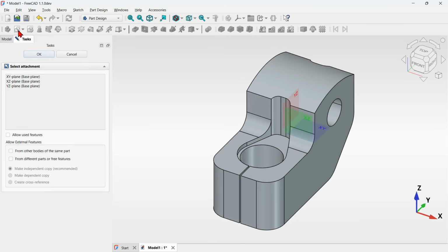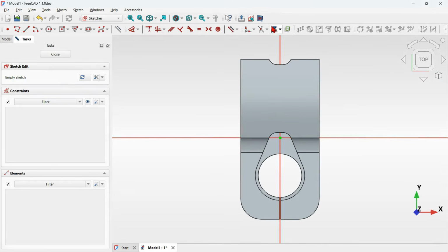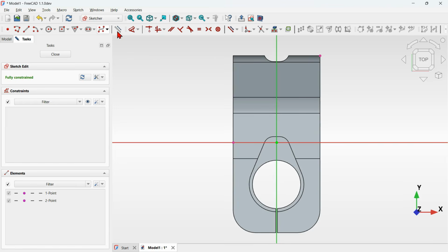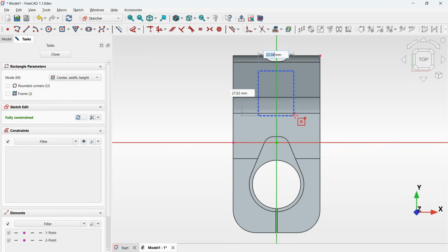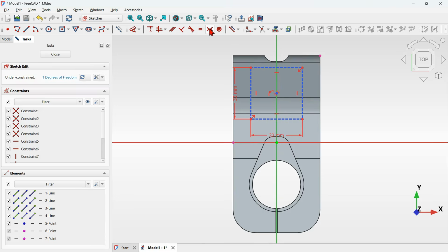Let's create another sketch, attach it to the XY plane, double click XY plane. Let's use the external projection geometry to import this point into the sketch and this point here. Switch to the section view, change to construction geometries, select centered rectangle, and let's create this rectangle with 32 millimeters by 32 millimeters, and skip the tool. And now let's select the constraint symmetric and select this point here, and the center point of this rectangle.